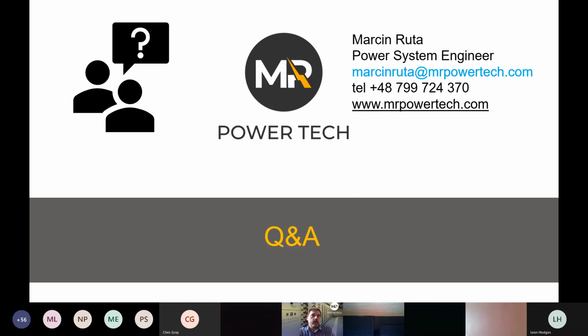you know the results. I did a project recently like this for 20 kV. So we know the results. We know that there was internal arc classification. Now, if you work live, so you have to do voltage testing, for example, or an absence of voltage test. Let's say you have an old switchgear. So for now, you have to wear your PPE, do it, drop it, and then you can work.